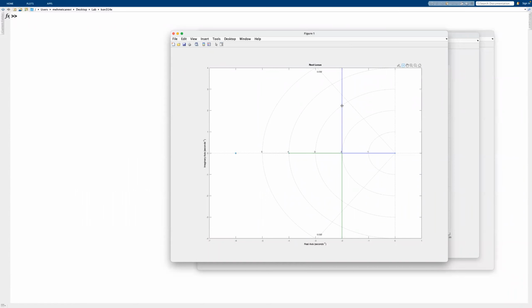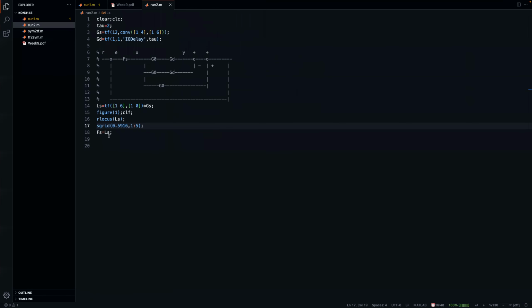I can just use this pole zero cancellation. Seems like somewhere here you can see 8.93. If I drag it a little bit more, 11, that's not good. So, well, 0.9. Yeah, 0.9 seems to be working. So let's say 0.9 times that should be our controller.